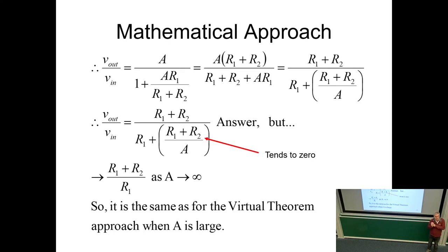Have you done the op-amp lab yet? So you've seen that the frequency response tails away. So if you're applying this at high frequencies, then A may not be large because the frequency response has dropped away. Under normal conditions, you can assume that A is large if you're assuming that the op-amp is going to be operating in its linear region, which is most cases for linear amplifiers. It's only if you're going up to high frequencies that you've got to start looking at your assumptions, because then it might not work as you anticipate.